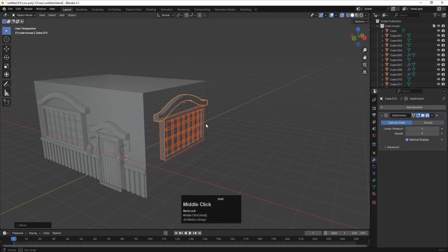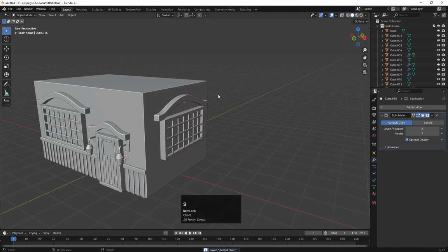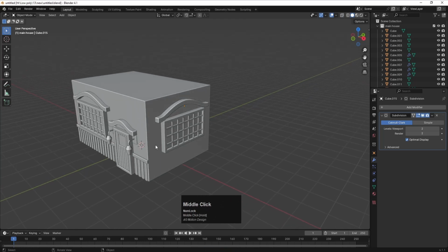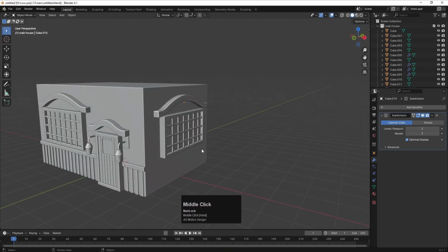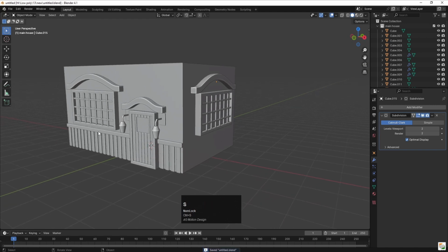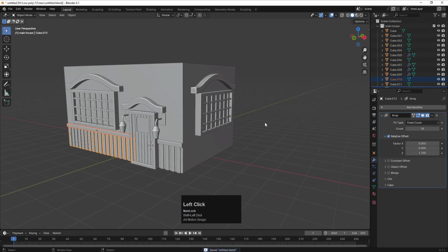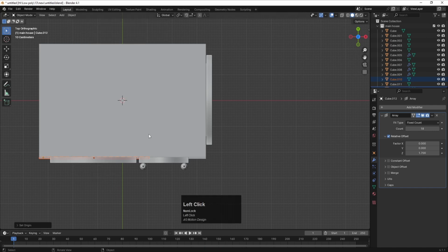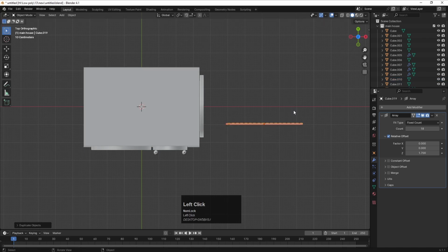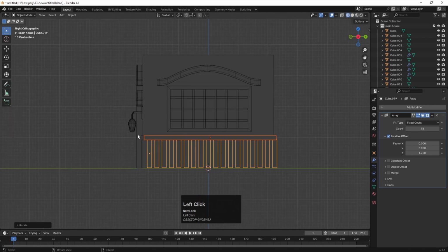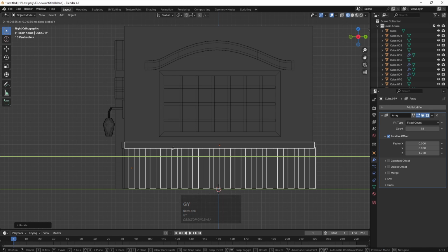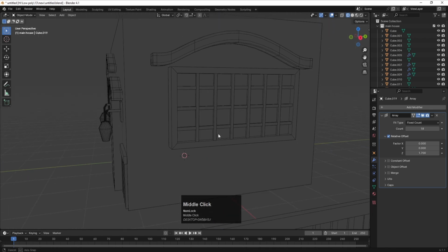Similarly in front view, yeah, okay, and alt set. And because we are not going to back rendering anything or 3D rotation, that's why I'm not going to repeat the structure at the back. Only this much portion I want to render it out. Okay, so that's why I'm going to select this and this. Let's go to the top view again. Object, set origin to the center of mass, shift D, bring this over here, R minus 90, go to this view, Z, choose wireframe, G, Y, and it should start from here to here, okay, like this.